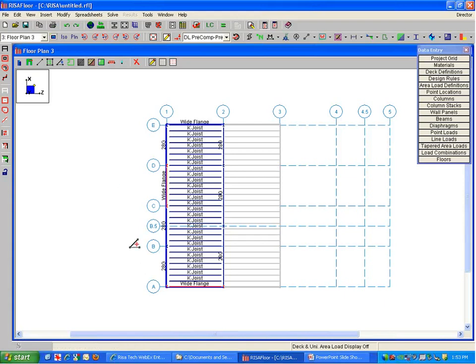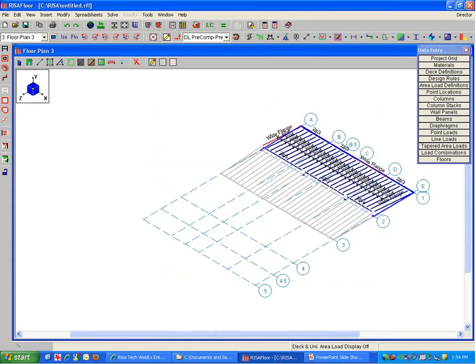So with this tool, I click on one point, and then it gives me this big red line across my screen. And what it's looking to do is create a plane. So if I tell it the plane is this direction, it's going to slope anything that is selected 1 on 12 from this plane as the base point. So I click on that point, and let's see that I did that correctly.